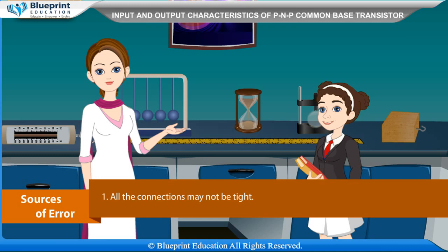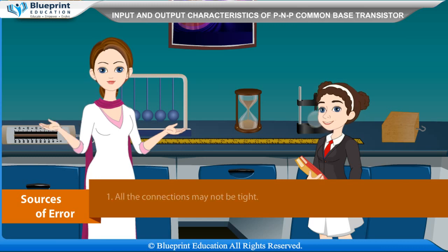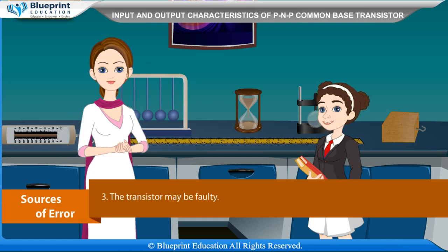Sources of error. All the connections may not be tight. Biasing of the transistor may not be done correctly. The transistor may be faulty.